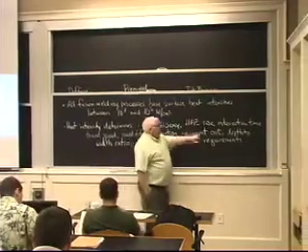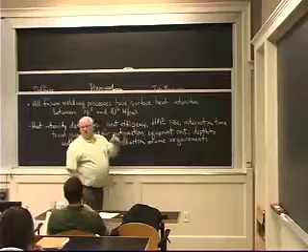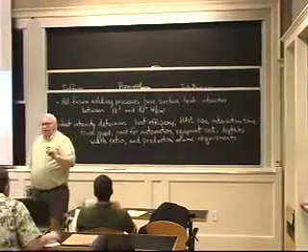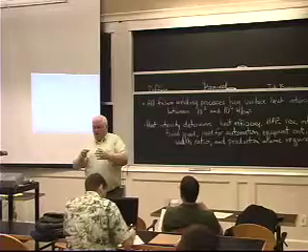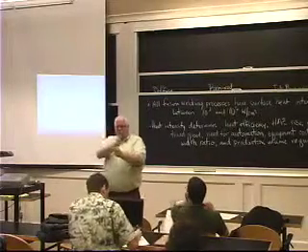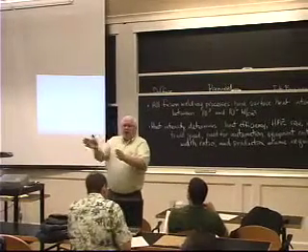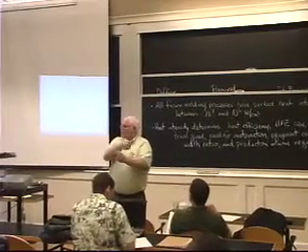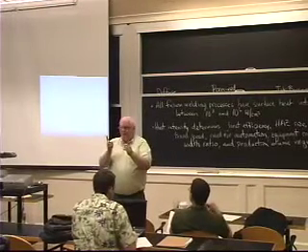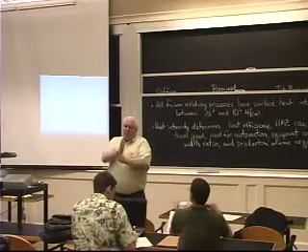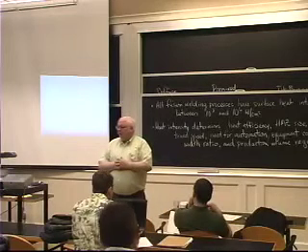The interaction time, which is just the size of the weld pool divided by the velocity of travel. If I'm traveling along and a weld pool passes point A, the front leading edge, how long does it take before the trailing edge passes that same point? The length of that weld pool divided by the travel speed is what we call the interaction time.